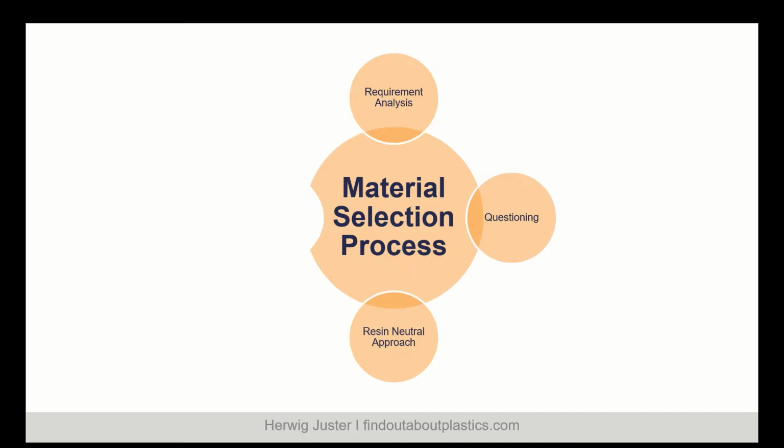And also it happens when you ask molders why they use exactly this resin for the part. Often the answer is, this resin is our house resin, so we used it and it works. And so therefore I encourage you to challenge your material selection based on those legacy materials, and combine it with the question, what do you really need in terms of requirements fulfilled, and why did you choose a certain polymer resin in the first place? So these are two key questions which need to be asked in this context.